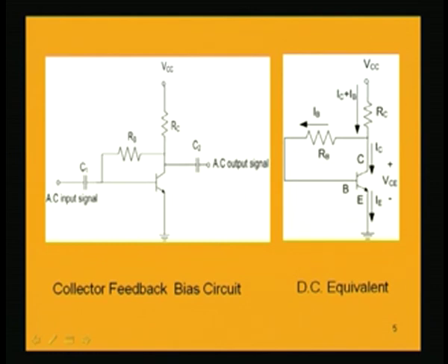So, we need to find out for this biasing scheme what is the collector current and what is the collector to emitter voltage, in order to know the operating point Q, which is known as the quiescent point or silent point, meaning without any signal, when we first find out the DC condition. When you apply the signal for amplification, then of course we will have to analyze it in a different way, drawing the AC equivalent circuit, and that we will be taking up later. For the time being, let us find out what will be the IC current and what will be VCE.